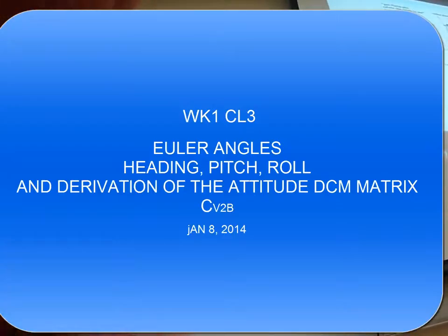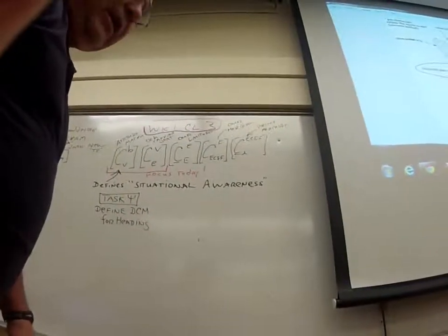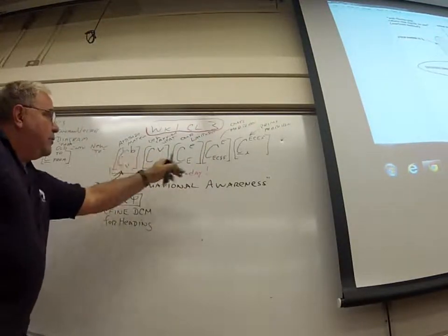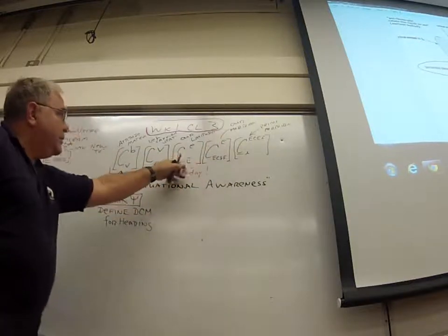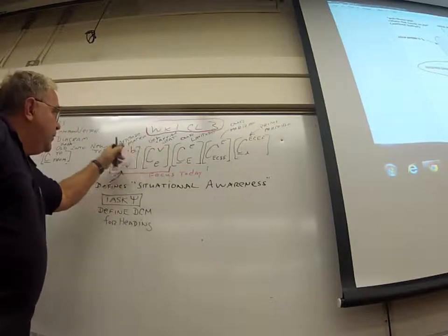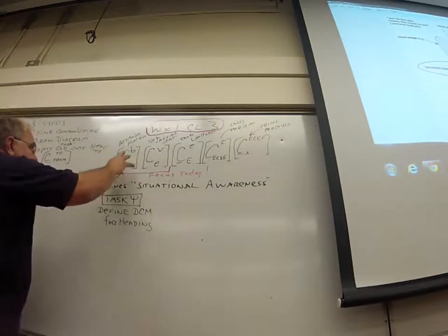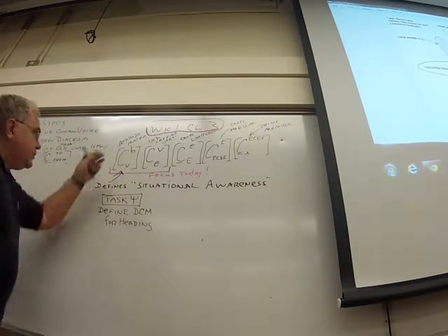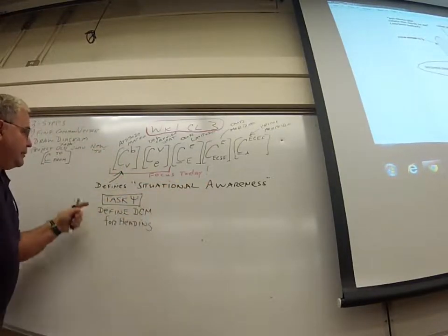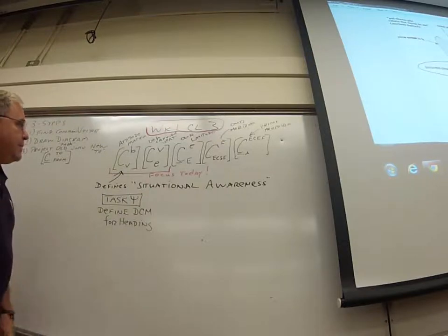All right. So, using that picture, which we'll start with, our job today is to locate ourselves in this patch, going from the inertial frame through ECEF (capital E, little e), longitude, latitude, vehicle carried vertical, to the body axis. And now we're interested just in this last attitude matrix, that attitude matrix which we call the definition of situational awareness. And the first job is to define heading.